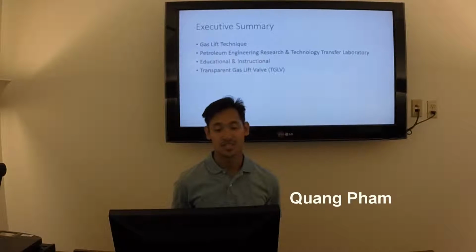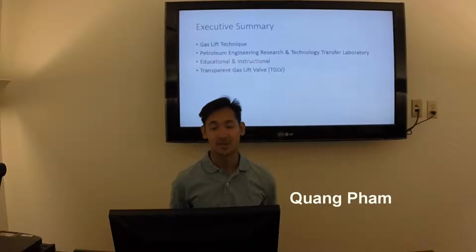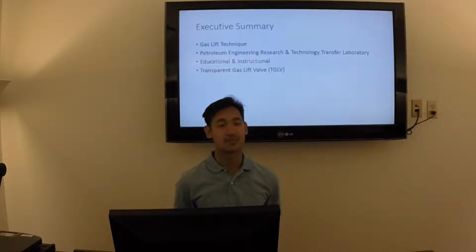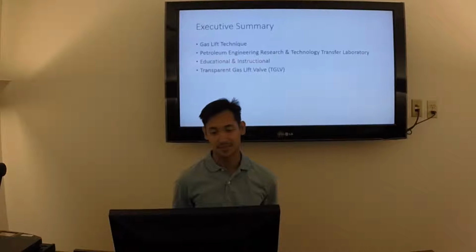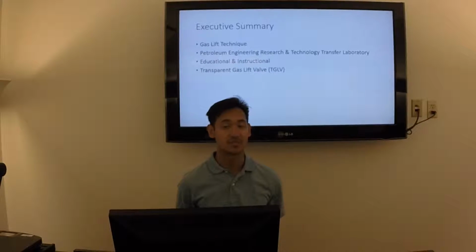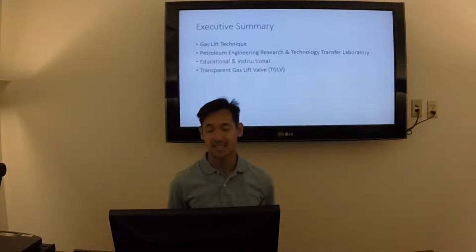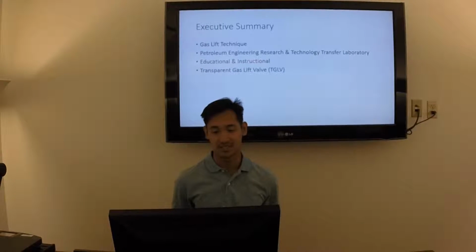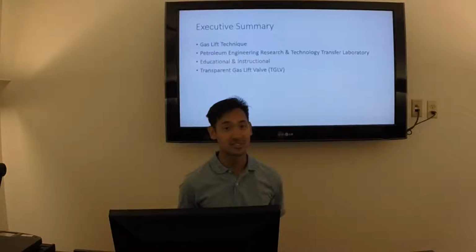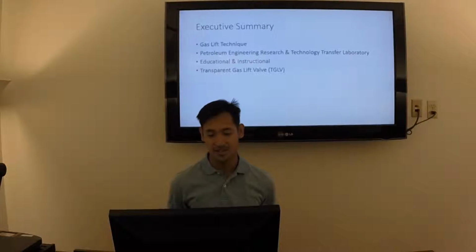Gas lift uses a technique in the petroleum industry known as artificial lift. This technique raises a fluid such as water or oil by pumping bubbles into an outlet tubing to increase the performance of production. This technique reduces the hydrostatic pressure in the outlet tubing and increases the pressure of the inlet